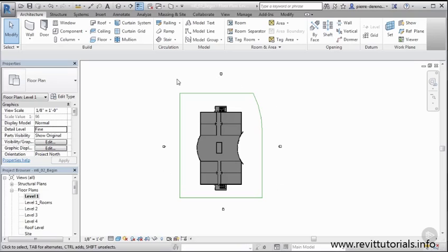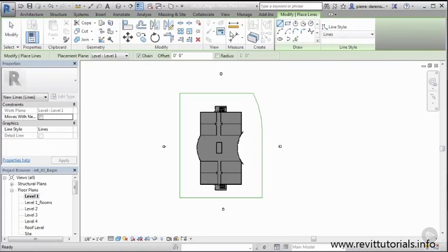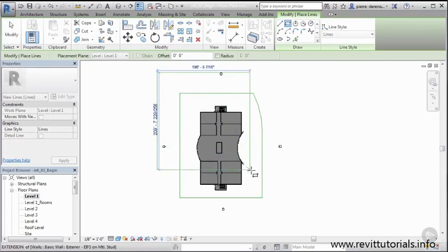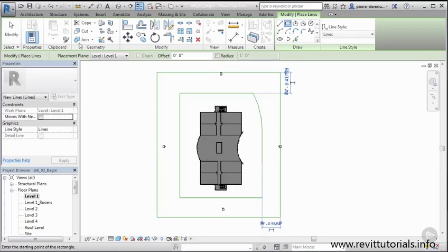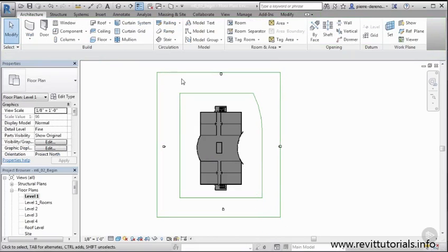So we're going to set up a couple of views, and I'm going to use a nice rectangle to set up 4 views. So let's go ahead and in our architecture tab, I'm going to go to model line, use my rectangle tool, and just, not very scientifically, I'm going to try to stay somewhat of a good distance away from my model. But the main thing is I want to try to keep my model centered within this rectangle that we just drew. And again, the positioning of my cameras are going to be 1, 2, 3, and 4. Now your camera won't snap here, but this is more of a scientific approach to the placement of my camera than just bringing in a camera and just dropping it in arbitrarily.